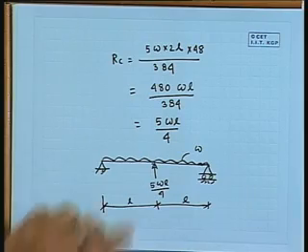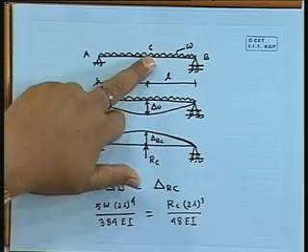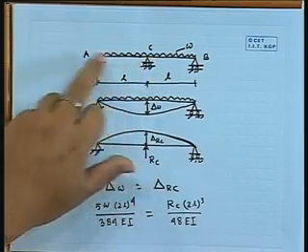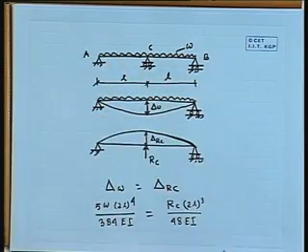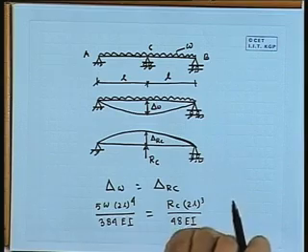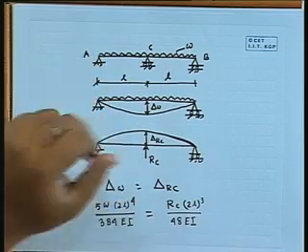So far we are handling a problem where the degree of indeterminacy is 1. So extra unknown is 1. So cantilever beam, the end reaction we have removed. Here the central part we have removed. Here I want to mention the central reaction we have removed. So not necessarily that is the only alternative. So if we come to the original problem, so here this was removed by a force. We could keep the support, remove this one, and put a reaction here. That can be also done, or we can keep this support, remove that, put a reaction there.